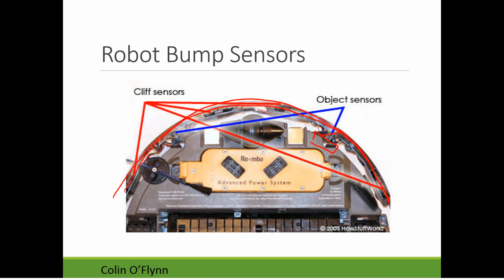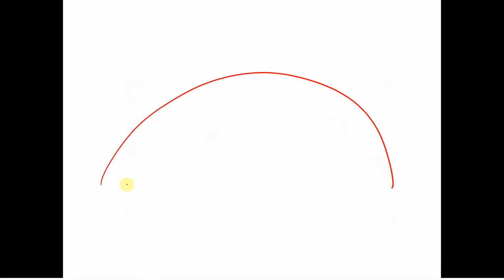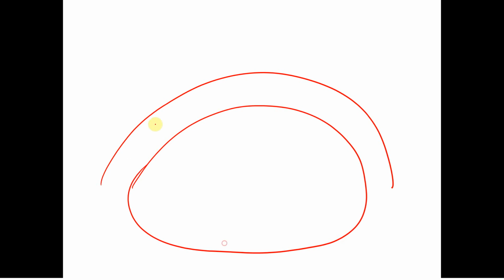And the idea is that, let me draw this better. So you have your robot base here. You have the micro switches, and you'll have to support it properly. But if your robot runs into something, if there's pressure here, it'll hopefully also hit that switch in. If there's pressure up here, it'll also hit the switch in. So you can try to set it up such that no matter where it hits, it's going to depress some of these micro switches.